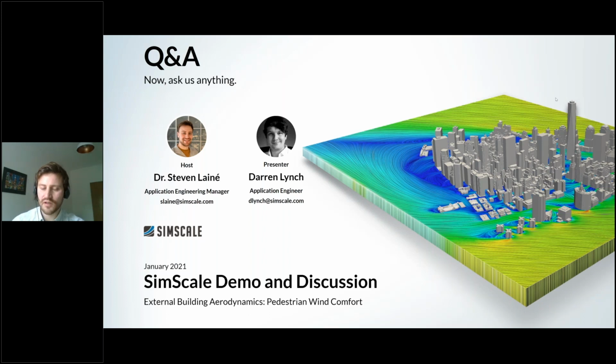Okay, so we've got a follow-up question on that previous one, Darren. Saying, what if I need to view results at 6, 9, 15 or 20 meters per second? What would be our solution there? Yeah, so if you did want to view those results, then there's nothing wrong with you scaling it yourself. What we would typically do is scale it by doing the velocity divided by the reference velocity and then multiplied by the velocity that you actually want to see.